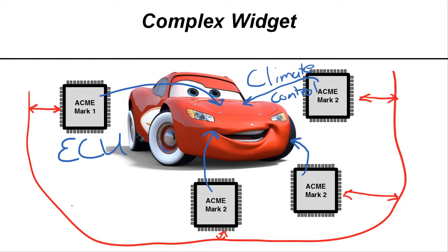They will have to communicate over a large bus. Now, for example, in automotive, a very popular bus, because it's very robust, is called CAN bus, Controller Area Network. It's a neat bus made of 2 wires that you can send little packets or messages of data between a bunch of different nodes.